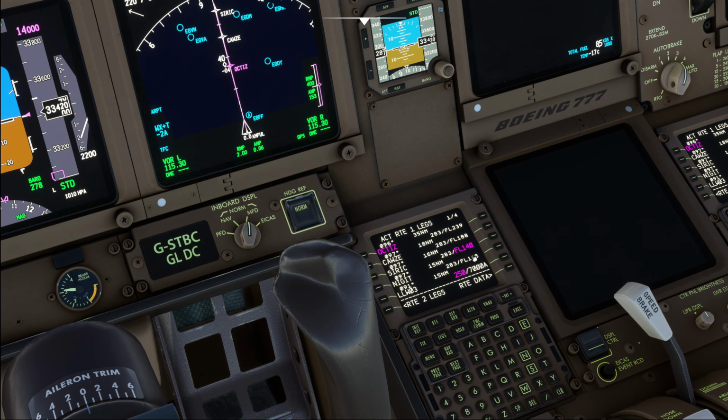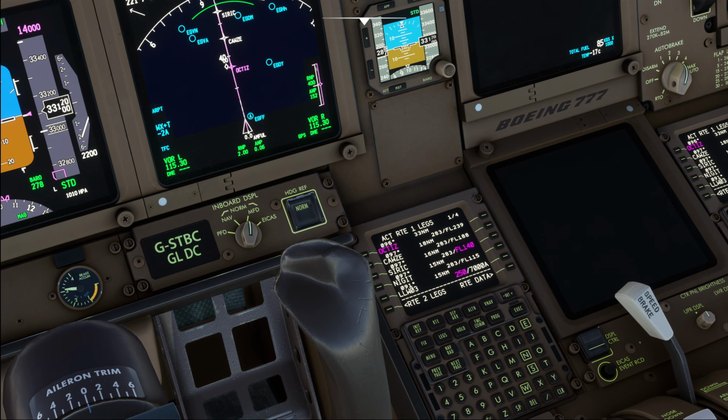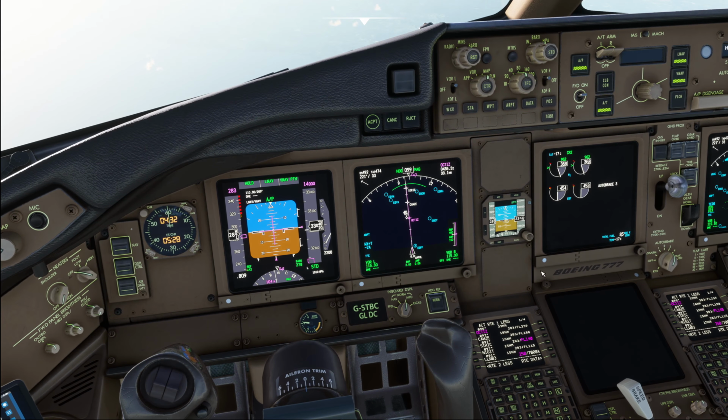And basically, ignoring all the restrictions, our current descent path starts right up here at the flight level 140 restriction at Zurich. And above that, it's calculating an idle path descent based on the amount of drag that the plane is expected to have at the airspeed that you have programmed as part of the Econ speed.